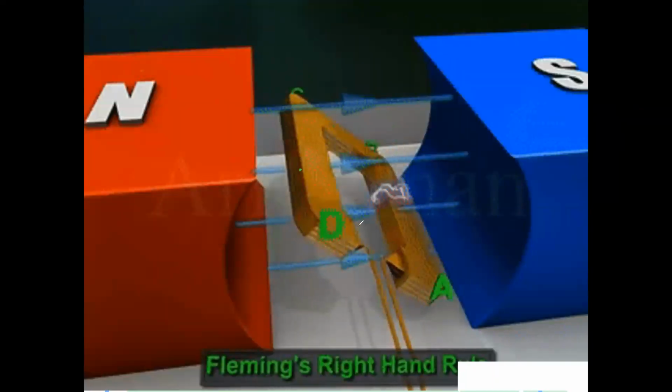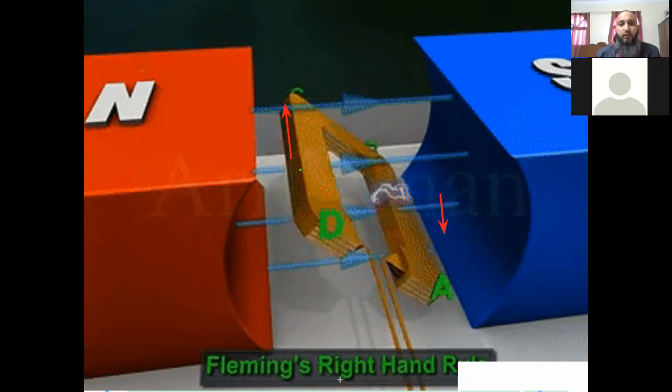So as the positions change, now C and D are on the left-hand side and A, B are on the right-hand side. Again, I will apply the rule. Now the direction of rotation is C and D moving in this manner and A, B moving down. That's the direction of the motion of sides A, B and C, D. So again I will apply Fleming's right-hand rule. For C and D, the index finger should point towards south. My thumb is pointing in the direction of the motion, which is upward.